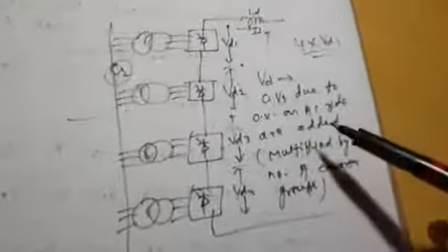So that means if overvoltage on AC side has occurred, it will result in multiplication of overvoltage on the DC side by number of converter groups. So a very large overvoltage will occur on the DC side. So this is yet another cause of overvoltage due to disturbance on the DC side. Actually, it is because of disturbance on the AC side which is reflected on the DC side.